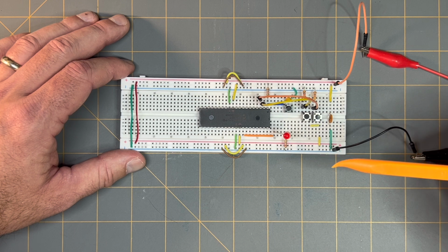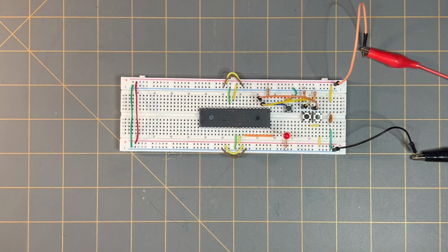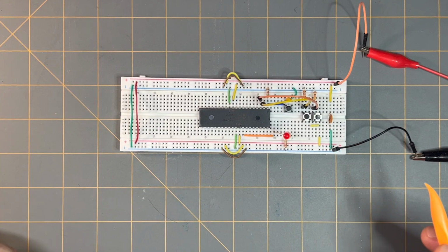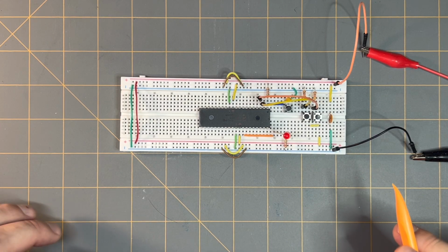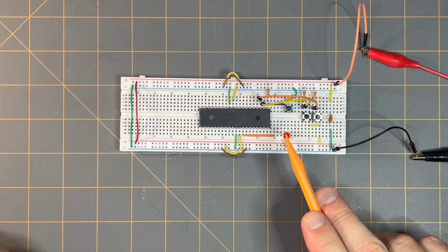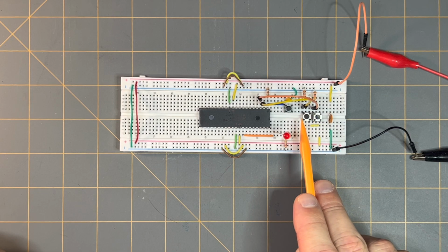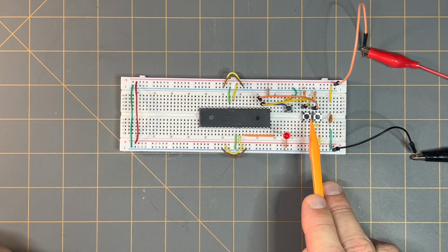connections of the LED to pin 33. So to complete our prototype circuit, all we need to do now is make the connections for the LED. We'll control it with the two switches here. That's switches 1 and 2 that we just previously added to the breadboard.